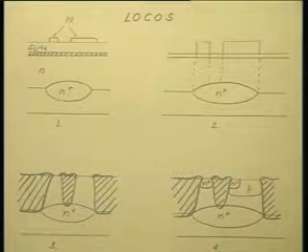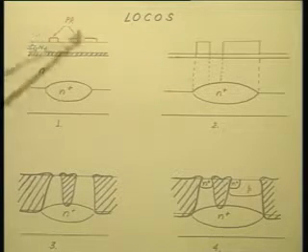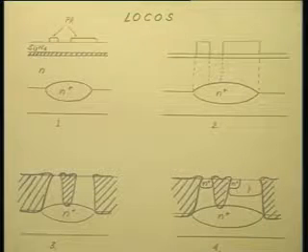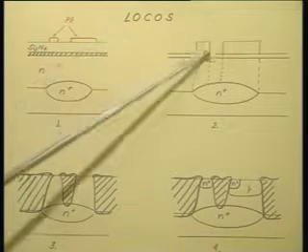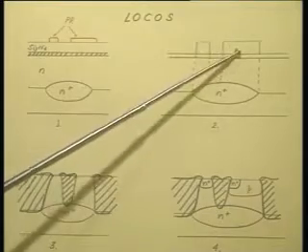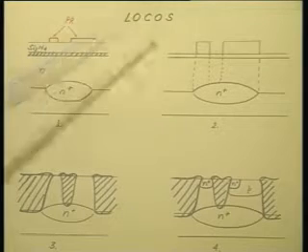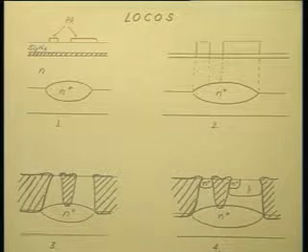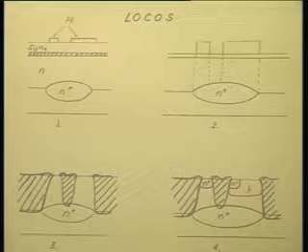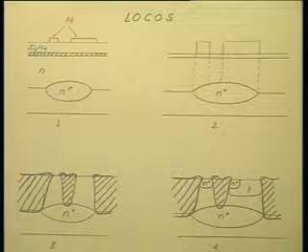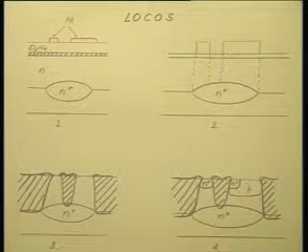In the next figure, using these photoresist masks, I have etched silicon nitride from the remaining portion. So, that I have silicon nitride only existing in these two regions and underneath there is this pad oxide, and silicon nitride is etched from all other regions. So, now you see the equation is very simple. The regions which are not protected by silicon nitride will get oxidized. If I subject it to oxidation, the regions which are not protected by silicon nitride will get oxidized. However, there is a slight problem.